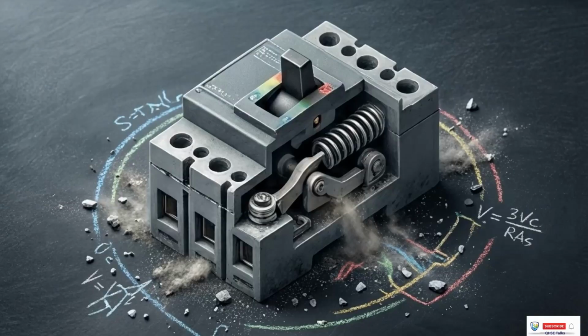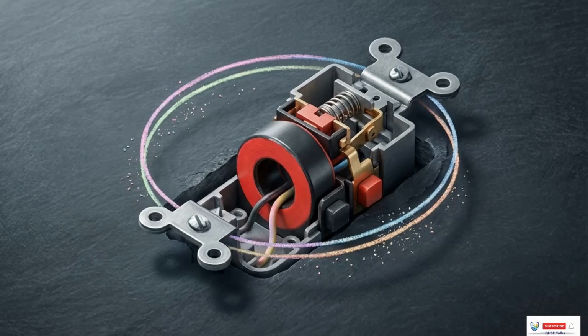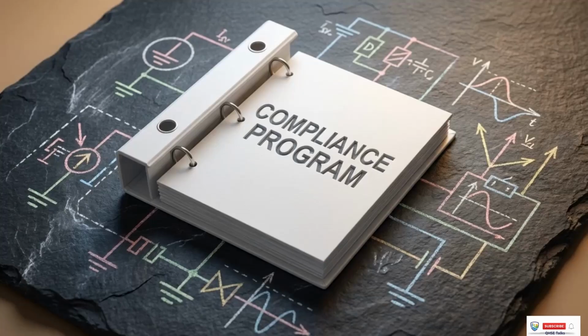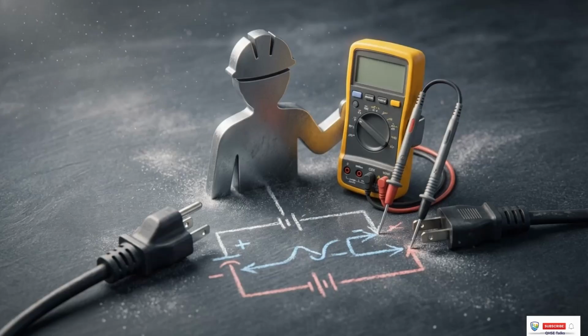This 3D cutaway shows a standard circuit breaker tripping. Breakers are designed solely to protect equipment and wiring infrastructure from massive overcurrent that could cause fires. This GFCI outlet is designed strictly to protect human life. It detects microleaks as small as 4 to 6 milliamperes and severs the connection in as little as 1/40th of a second. In construction settings where GFCIs are not used, the law requires a written Assured Equipment Grounding Conductor program. This must be managed by a designated competent person.